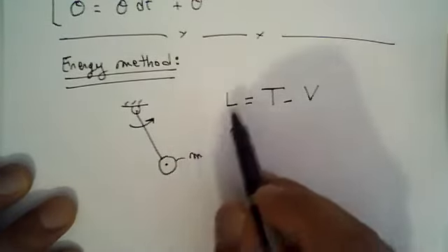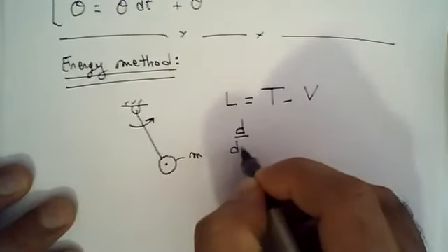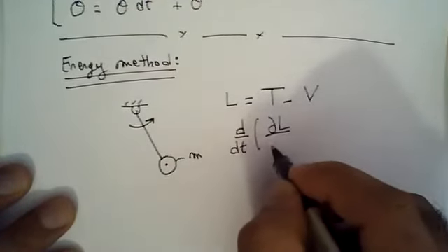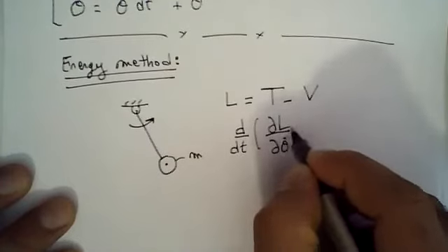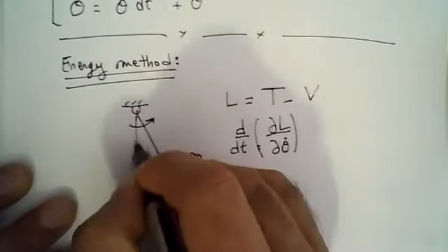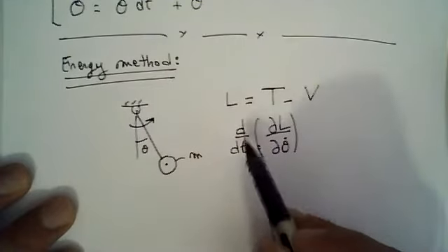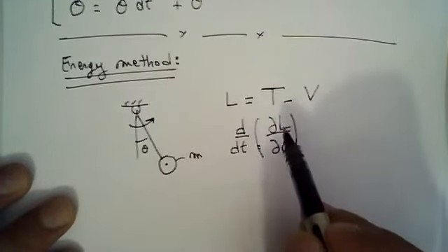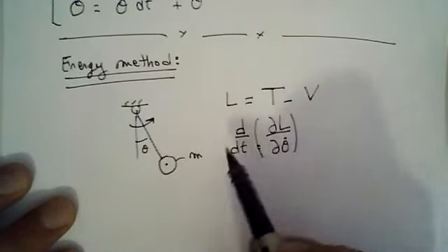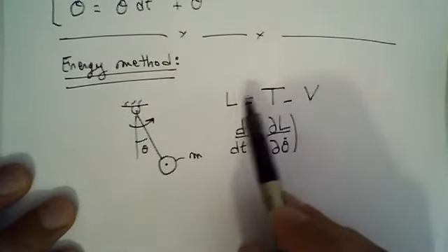All right, and when we want to obtain a differential equation of motion, here's what we'll do. We're going to differentiate this guy. So we'll take the partial derivative of Lagrange with respect to the velocity, and we apply this on every degree of freedom. So this is my theta, let's say. I differentiate Lagrange with respect to theta prime. So d over dt of the partial derivative of Lagrange with respect to the velocity of the first joint. I could have 5 or 6 joints, and I can do this over and over again. Lagrange will not change. This is for the whole system.